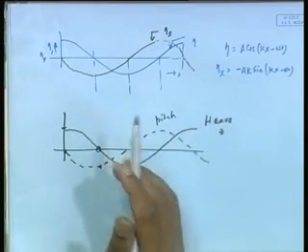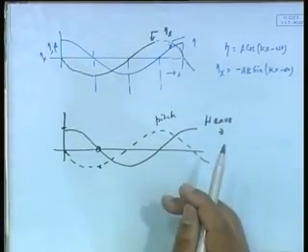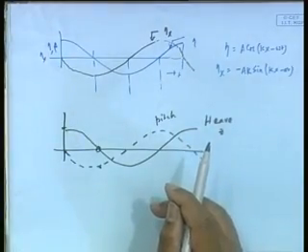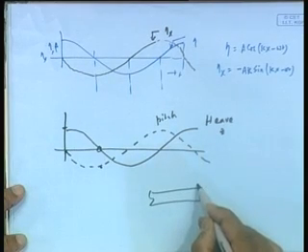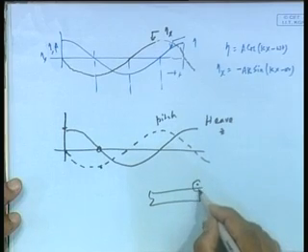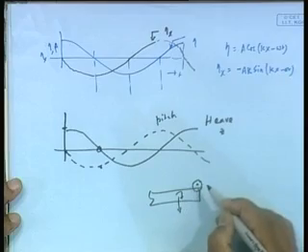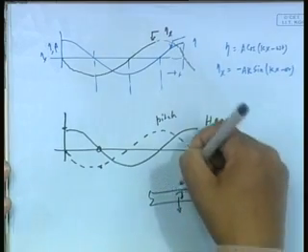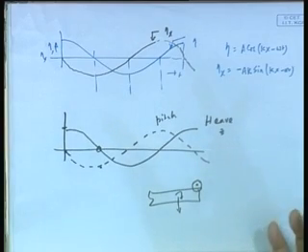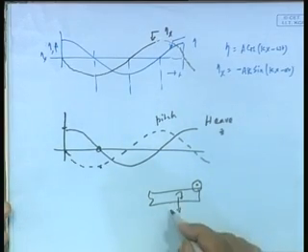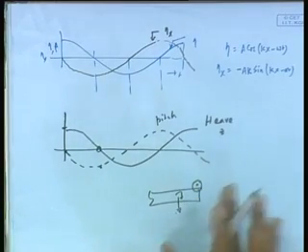This is important, because when I want to find out what has happened when you are standing at some point, phase is important. I cannot add all the maximums together. I am standing at this location. We will discuss this later on. The ship goes down, and the ship also comes down. Supposing at the same time the amount it went down maximum, it came down maximum, you would have been much lower, but that is not happening. Usually they don't happen together. Why? Because there is a phase gap. The concept of phase is therefore very, very important.